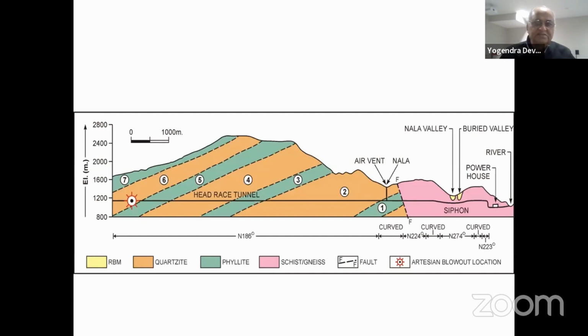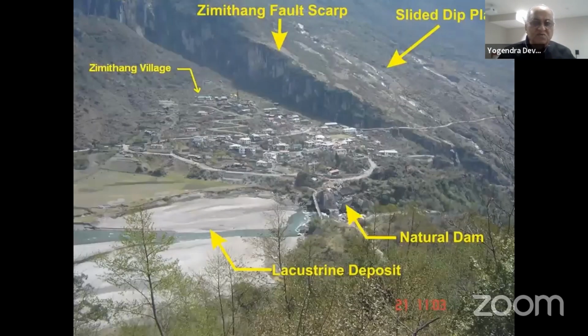Likewise, in the synoptic stage itself, you can prepare a geological section to show what is there in the subsurface. The map was shown earlier. So you can see, at this particular project, there is a big fault here. There is a buried valley here. You can see there are again gneisses on this side, and an intermediate sequence of phyllites and quartzites on the upstream side. And this is the basic model which comes up within the first site visit by an expert and the young team, which is going to carry out the further work.